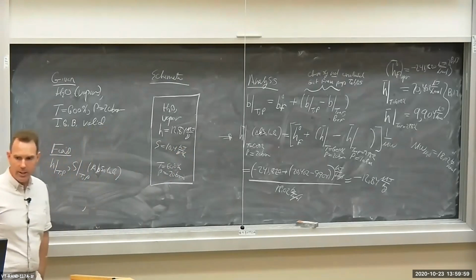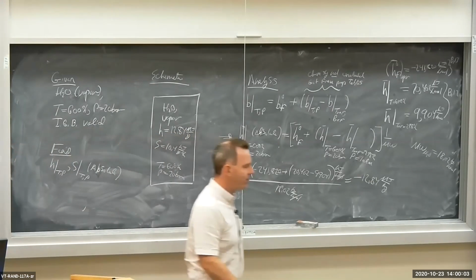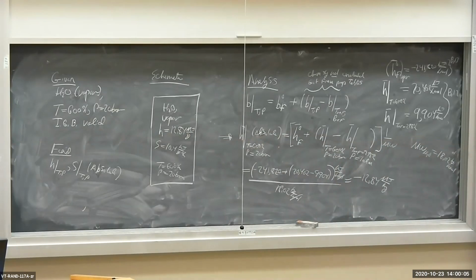All right, so that's how you calculate properties to include the effects of the chemistry. Now I can use these H's and these S's, specific enthalpy and specific entropy, in energy and entropy balance problems and calculate heat transfers, S dot gen, all sorts of stuff. So the chemistry is now included in the properties, which is what we want.